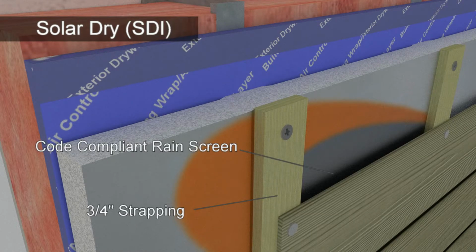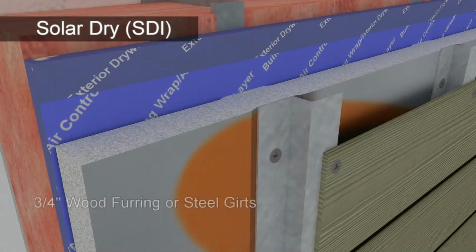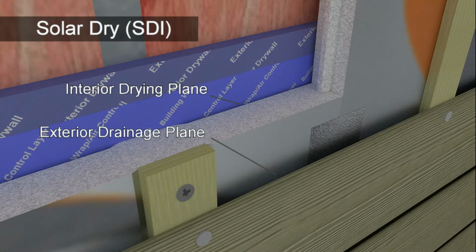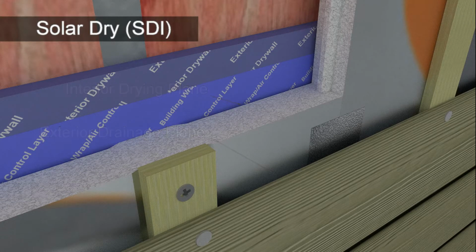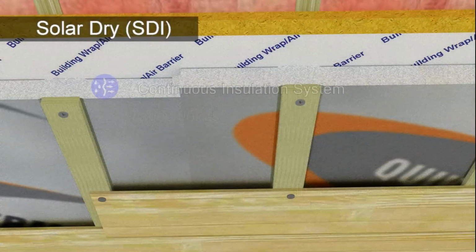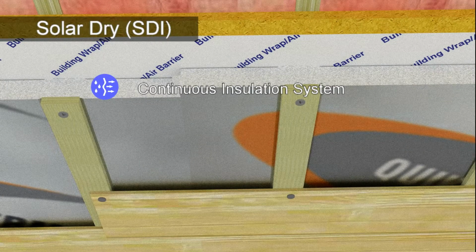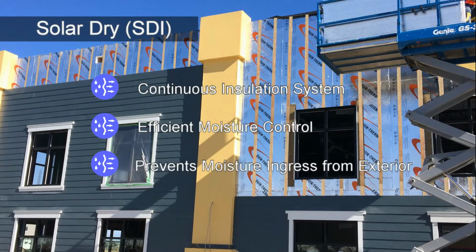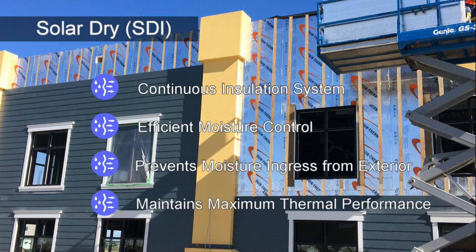The exterior polymer facers combined with a 1/2" airspace create an impermeable code-compliant Rainscreen. An interior drying plane and an exterior drainage plane, combined with impermeable polymer facers, result in moisture control on both the interior and exterior sides of the EPS core. As a result, a continuous cover of insulation can be achieved that will not compromise moisture control, will prevent the ingress of moisture from the exterior, and maintain maximum thermal performance.